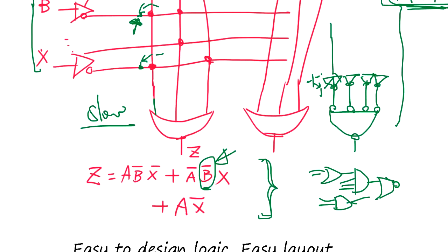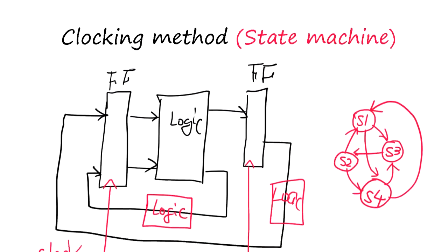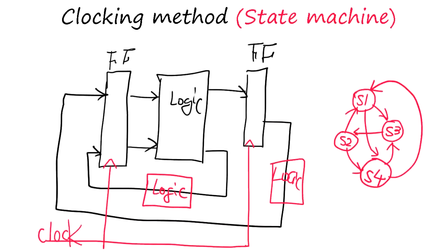But it's controllable, because if you put all the logic components together, the worst case delay is what you have to deal with, and often it's not that easy to find the worst case. You use software to find the worst case path for the worst case delay. Why is this delay important? Any logic design, we use a state machine. A state machine is, we have a clock.